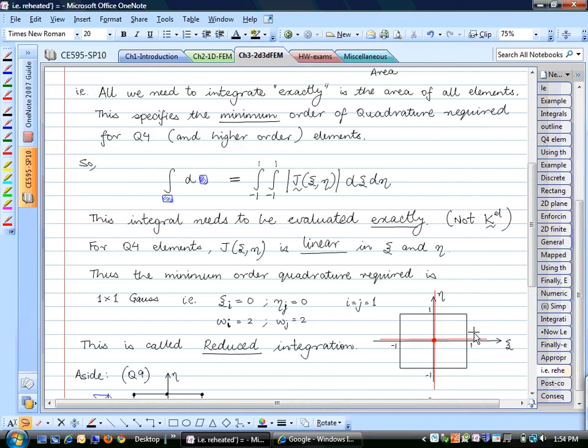And this is an important point. You will see a lot of times people show pretty pictures, as they like to call them, of some finite element solution. It doesn't mean anything. You have to make sure that you put that result into context. If I'm getting this solution for 40 elements, what is the solution for 160 elements? What is the solution for 2000 elements?